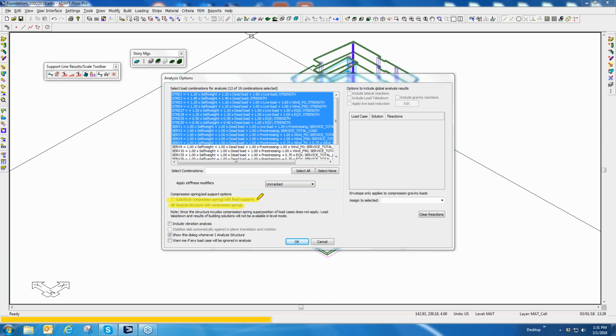When you run the model in direct mode, or use the direct solution, the program just assumes everything instantly appears and is all generated at the same time. So there's no sequential approach to the analysis. Another reason you might use substitution is that the analysis takes a much shorter duration, especially if you have a lot of combinations.